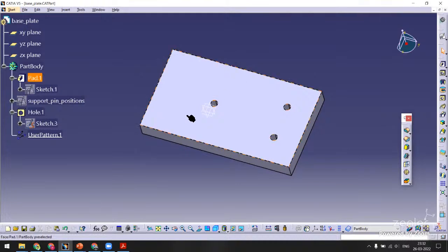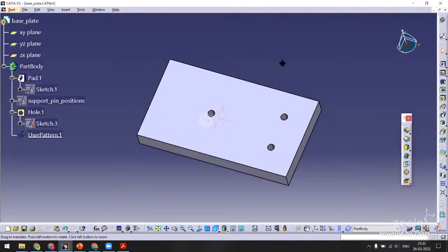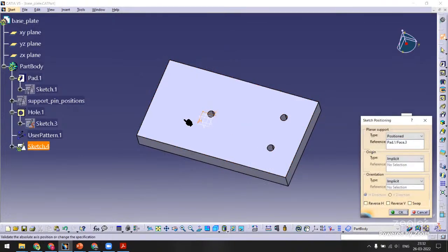So I'm going to put a cutout in the base plate. I'm going to make a position sketch here on the top surface of the base plate. I'm going to swap and then reverse V. I'm doing this again and again. I swap whenever I create, and then do the reverse V because I always want a top view, because there is repeatability.